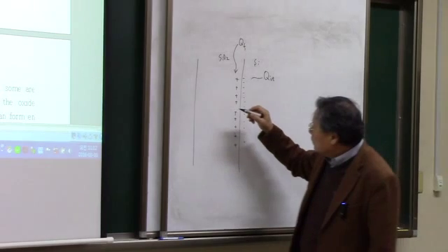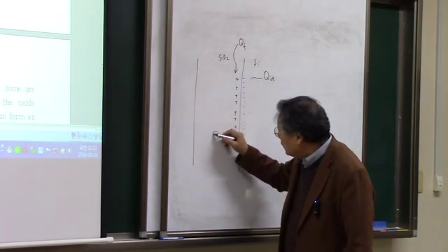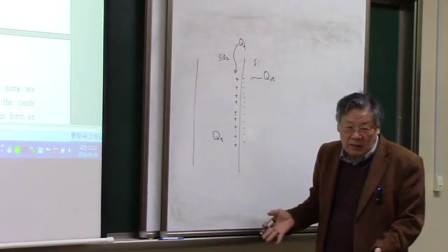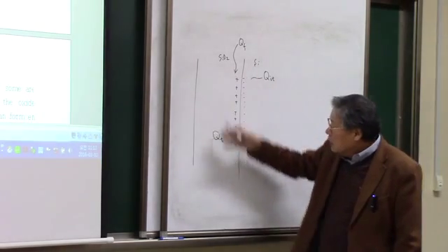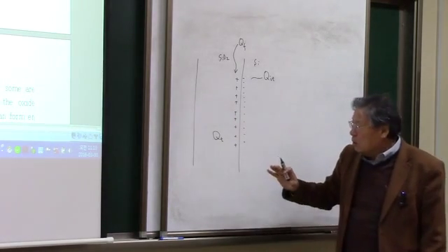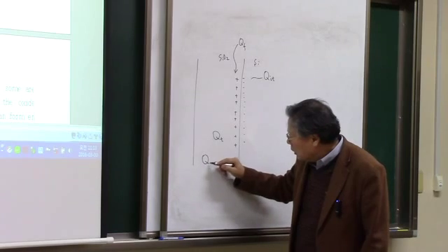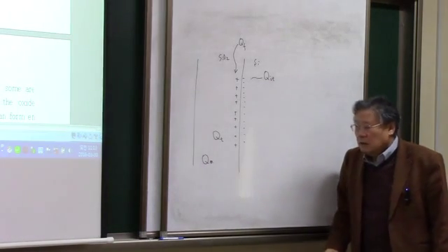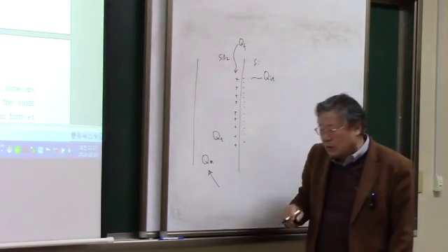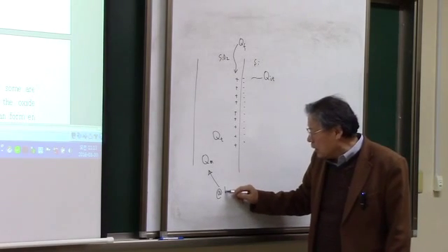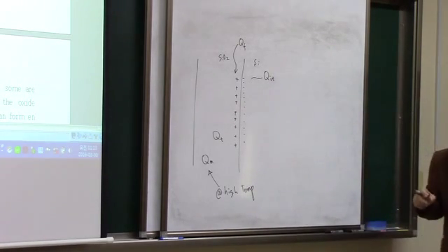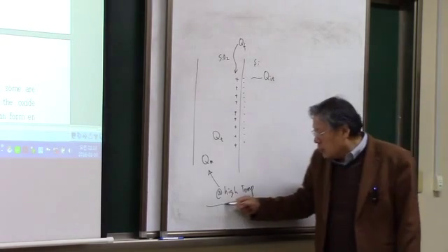So the amount of fixed charges and interface charges is about the same. And the other, oxide trapped charges, are just charges which are trapped, really, as the name says. They are just trapped in the oxide, so they are not moving at all. And we have another type, mobile charges in the oxide. And the mobile charges here are mobile at elevated temperature, at high temperature. Of course, at room temperature, the charges are not that mobile.